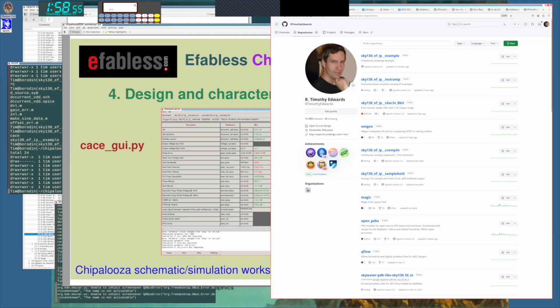Okay, Chris Meyer asked, when will these configuration files be available in a text file so we can copy? The answer is they're available already. Well, the ones here are available, and I chose the instrumentation amplifier and the RDAC because that covers most of the things that most people need, like CMRR, PSRR, current draw, power draw, and so forth.